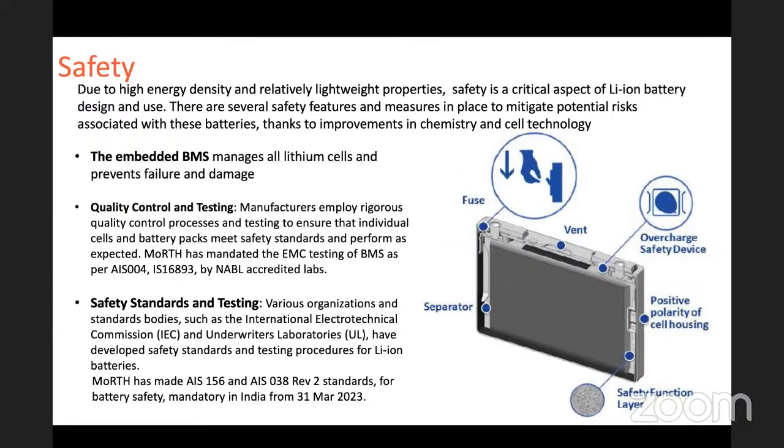Quality control and testing have also been introduced, and even the Ministry of Road Transport and Highways has mandated EMC testing of BMS as per the standards AIS 004 and IS 16893, and has mandated test reports from NABL accredited labs.